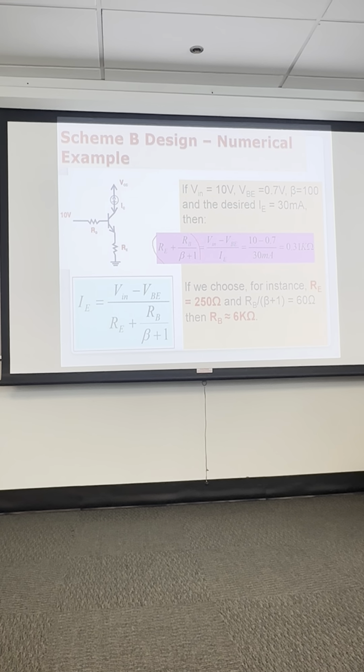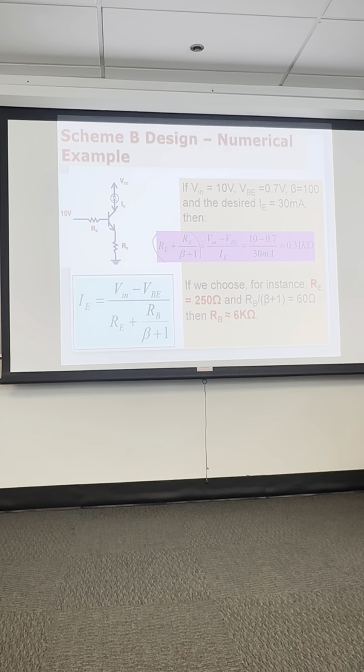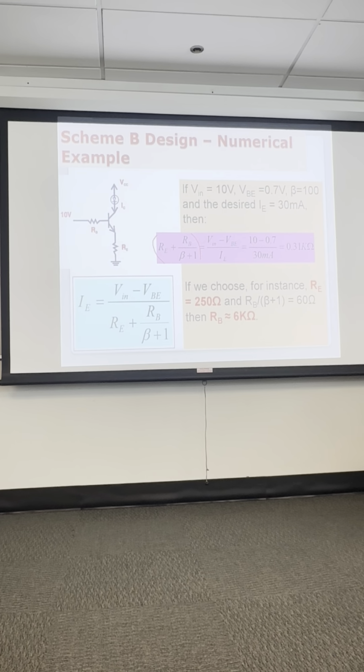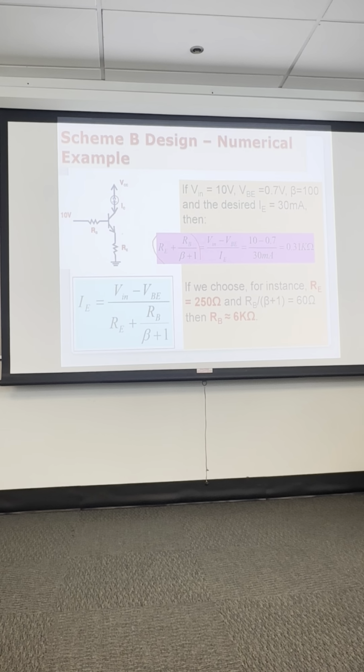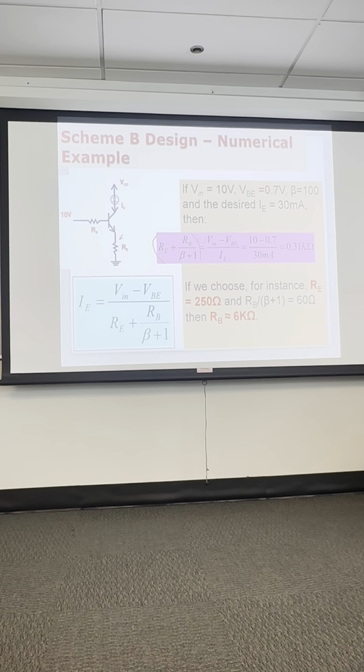So you obviously would not pick RB equal to 10 megohm. And why is that? You definitely would not put a 10 megohm resistor here. Why is that? Too much resistance? It would go into cutoff. Oh, good. There's no current flow. So large resistors don't work.